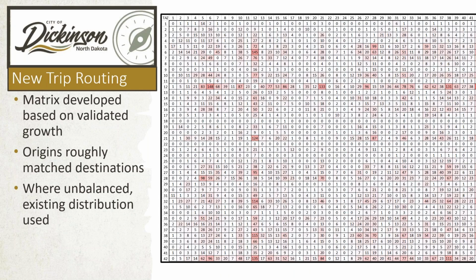And so once we had the trip generation, we had to assign these trips to each zone. So what we did was we had a spreadsheet where through multiple iterations, we were able to sort of match how many trips should be coming from a zone to what currently is. So we continually added vehicles until that difference was very small. So we combined the existing distribution with these volumes to apply the growth throughout the metropolitan area.